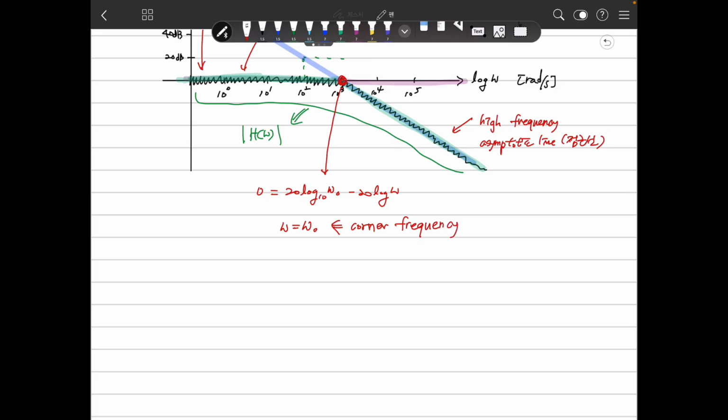So in the previous chapter, we called this frequency the half frequency. But another name for that is the corner frequency. Actually, the corner frequency is more frequently used. I told you that the half-frequency term only applies to first-order low pass filters, but the corner frequency can be applied to higher-order systems. Corner frequency means the point where the two asymptotic lines meet. We call that the corner frequency.